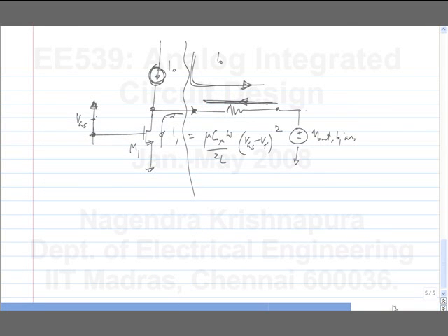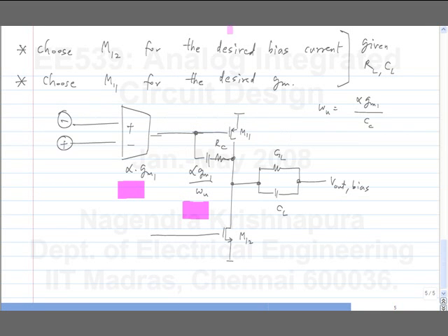Now, the total current consumption is I0 plus I1. You can ask, why don't I minimize I1? Why don't I make the second stage very small? But we have already said that we need a certain current in the second stage. It could come from the swing constraint if you have a resistive or a capacitive load. So to drive that you need a certain swing.